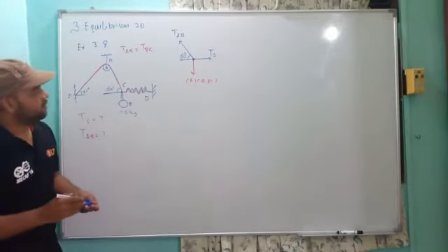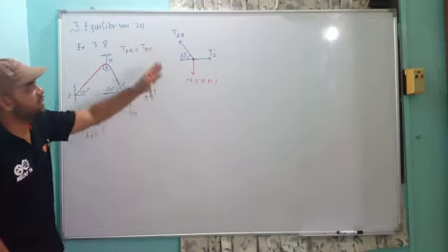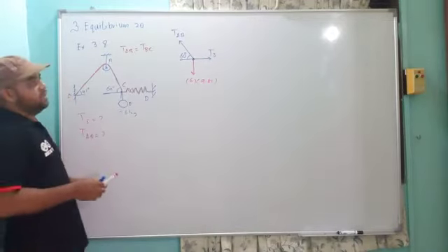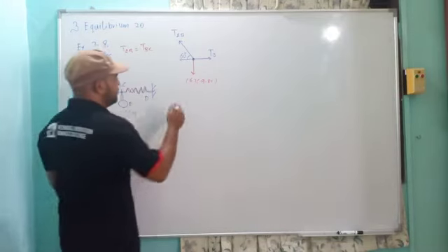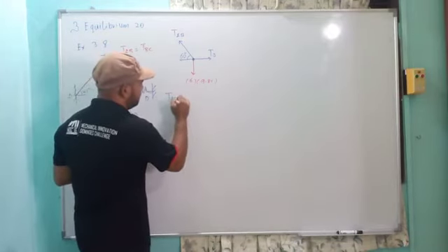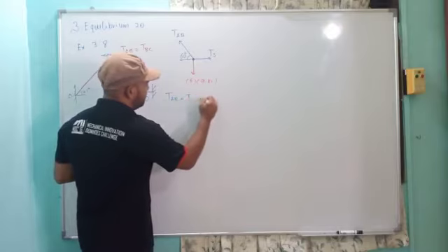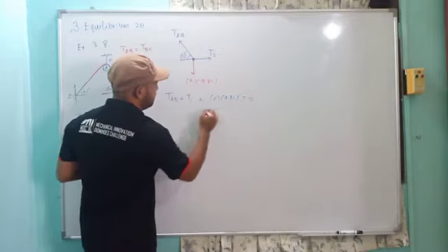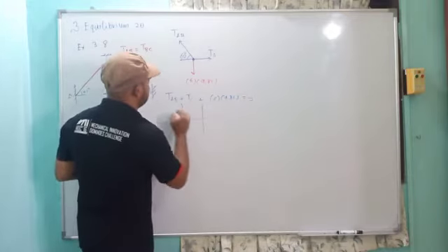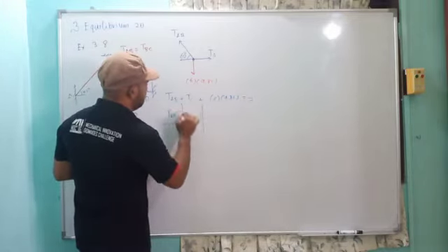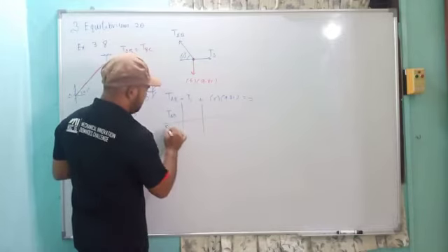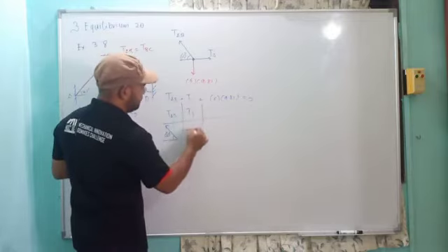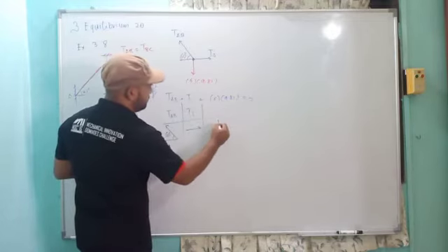So from here obviously you see that you have two unknowns, which are TAB and TS. Maybe you use rectangular components, so the equation is TAB plus TS plus 6 times 9.81 equals 0. The first unknown TAB is in this direction at 60 degrees, TS is in this direction, and this one is directed downward.